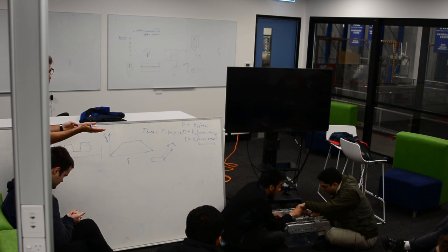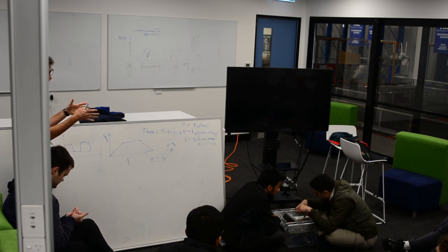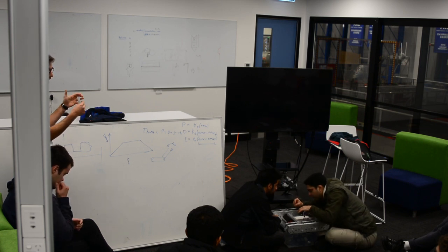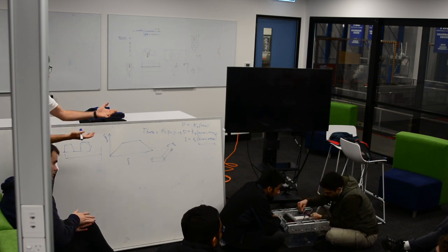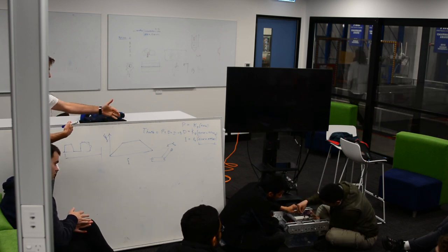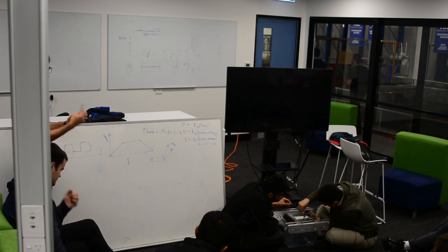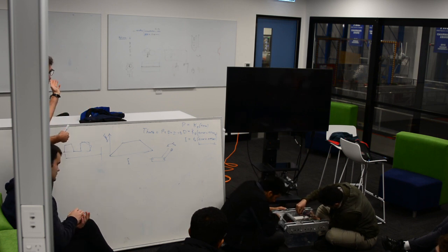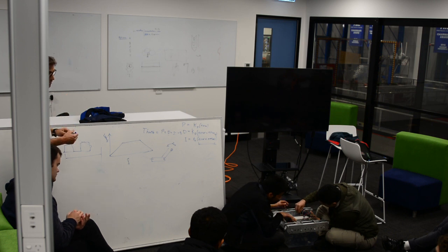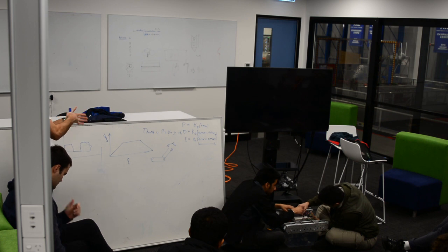Depending on how many other things you are doing at the time, you probably need to think about your robot as being in different states, right? You think of it as during this state, all I'm doing is driving forward. And if that's all you've gotta do for this 10-second or 5-second period, it's probably okay to have 4 interrupts going and doing it all at once. But if at the same time you're driving forward, you're trying to do Wi-Fi communications to the base station, probably not a good idea. So I would think of doing one thing, and then another thing, and then another thing, and don't try to do all things at once.